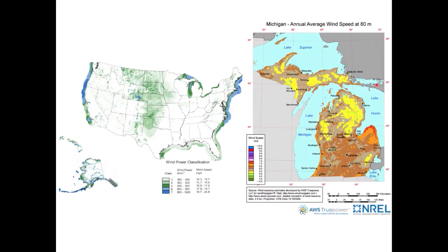You've looked at the map on the right-hand side of the screen in one of the earlier modules when you figured out how much electricity you could generate by siting wind turbines across the lower peninsula of Michigan. And I just want to highlight that when you look at the state of Michigan, where the colors, if we look at the legend, correspond to wind speeds, and remember, power increases as the cube of the wind speed or velocity, here given as meters per second. The ideal location to site wind turbines is the location that has the highest average sustained wind speeds.